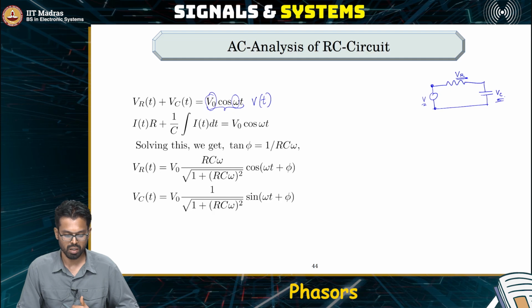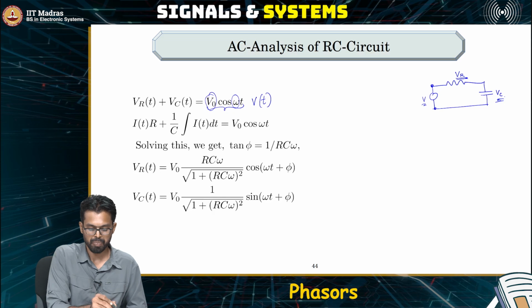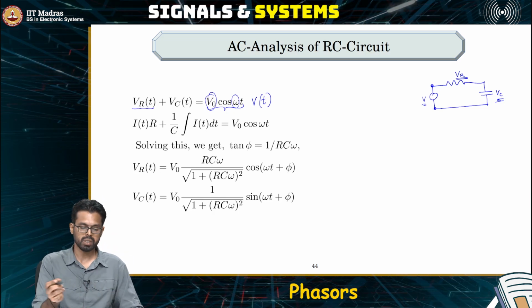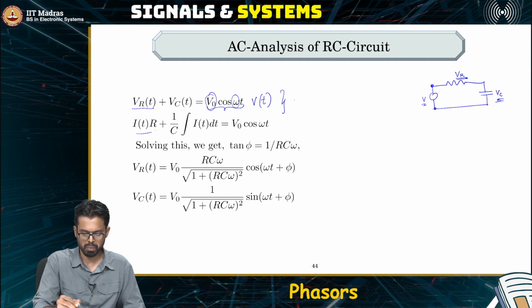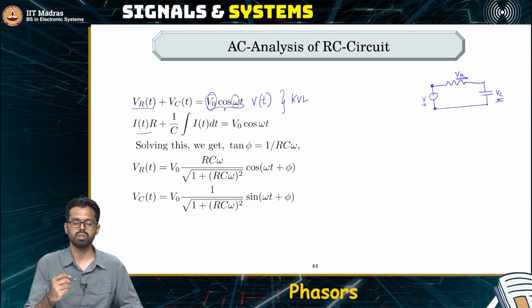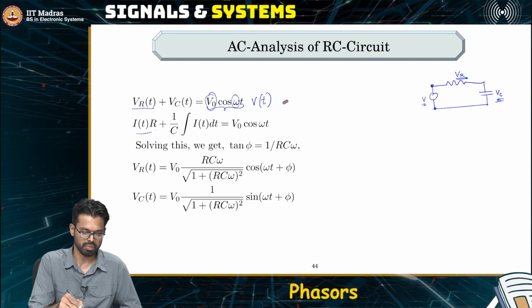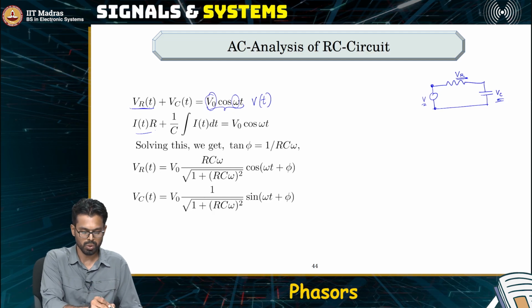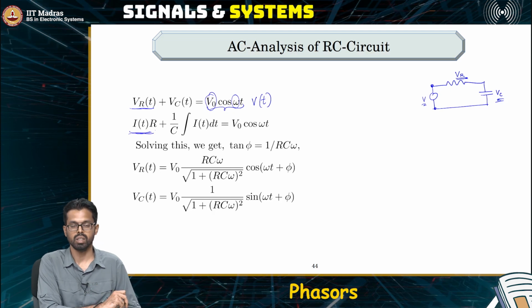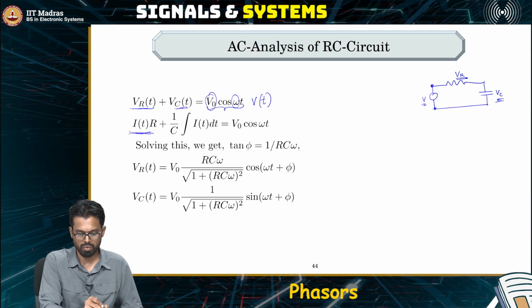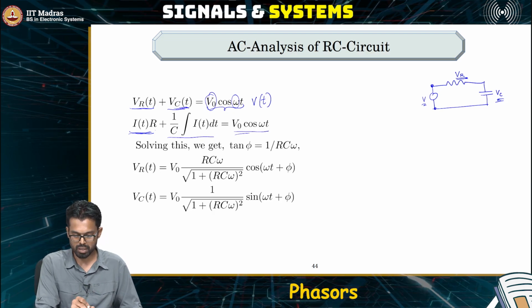We know this traditional equation, right? So V is equal to IR, we are going to just use that. So VR is equal to I times the resistance, that's all we have. So the first equation is basically nothing but KVL, Kirchhoff's voltage law. In this entire circuit, this has to be equal. So that's what we have done here. And we are just going to use Ohm's law for each of these voltage values. This is the voltage across the resistance, and this is the voltage across the capacitance, which you can write as an integral. And this is the total voltage in the circuit.